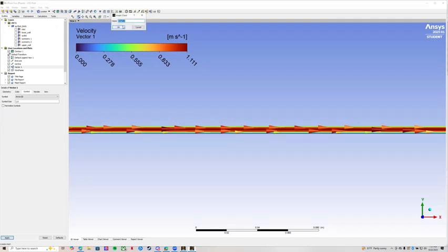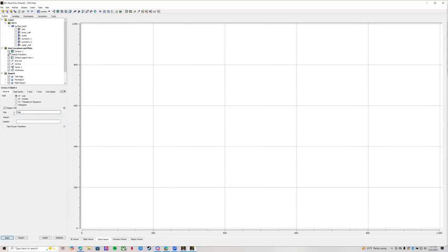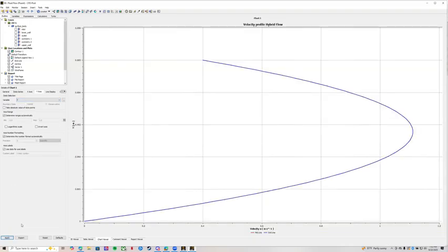We're going to add our chart in now to get that velocity profile. So we're going to change the chart title to velocity profile hybrid flow. And it's going to be an XY line data series. We're going to repeat the process again where we're going to go midline. And then we're going to add another one. It's going to be called our end line. We had our end line location. We have our 2 data points. Change our x value to velocity u again, and our y back down to that y value. Press apply, and there we go.